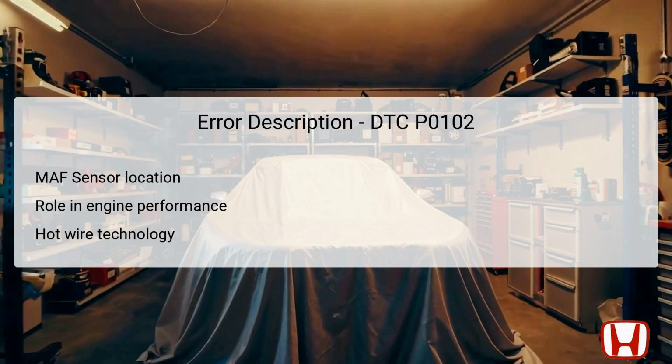The sensor operates using hot wire technology, where a wire is heated electrically. As air flows past this wire, it cools it, and the PCM measures the current necessary to maintain the wire's temperature. When the airflow changes, the detected current also varies, which allows the PCM to calculate the amount of air for proper engine operation. If there's a malfunction, like a low voltage output from the MAF sensor, it can lead to poor engine performance, reduced fuel efficiency, or increased emissions due to an incorrect air-fuel mixture being fed into the